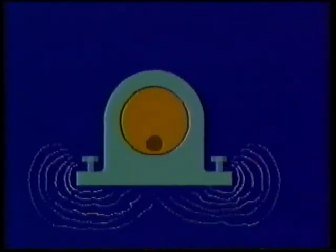To see why mechanical looseness produces vibration at both 1 and 2 times RPM, let's look at this simplified picture of an unbalanced rotating part. The amount of unbalance might be acceptable in itself, but it's aggravated by the mechanical looseness. This bearing's housing is loose, so with every revolution it's pulled upwards to the extent of the mechanical looseness by the rotational force of the shaft. Then, as the heavy spot rotates downwards, the bearing falls down to the base, again causing vibration. So every revolution generates two forces, which will show up at 1 and 2 times RPM.